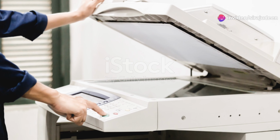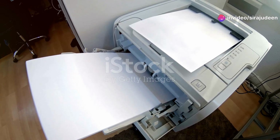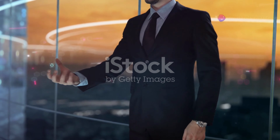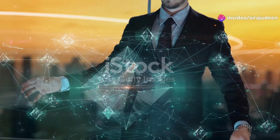Take printers, for example. They might not be running constantly, but when they do, they can draw a significant amount of power. A typical office printer can consume around 400 watts. It's crucial to account for these intermittent loads to ensure your system can handle peak demands without a hitch.